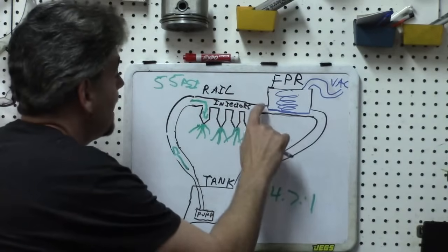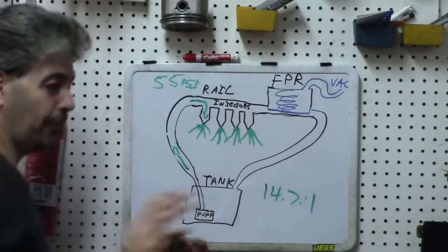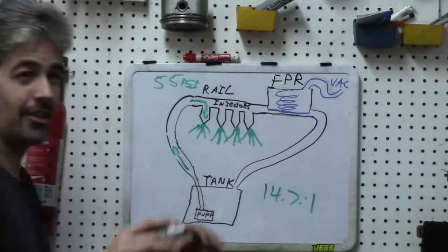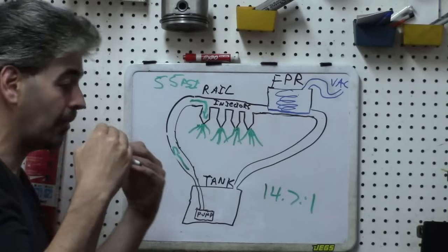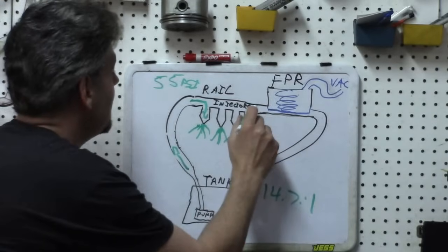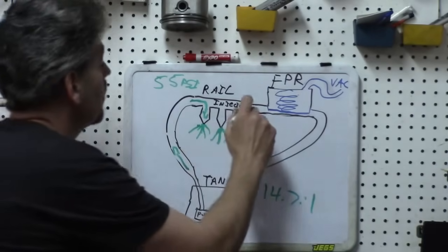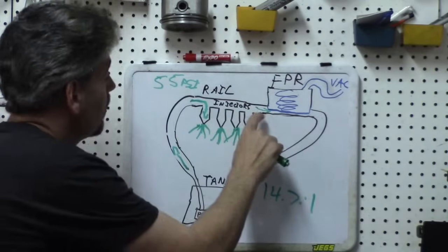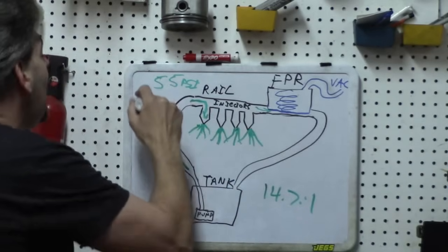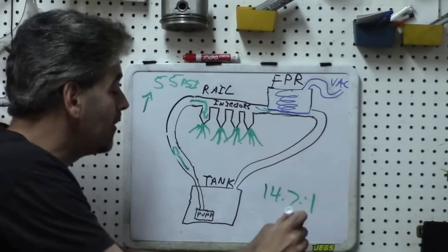You can see that what we've got here in blue is a diaphragm, and the diaphragm is connected to a spring. I know for those of you that are engineers or professional automotive technicians, you've probably been trained on this, and it's not exactly like this, I know, but the idea is to get the theory of understanding here. This is not an engineering class. But the idea is, by default, the fuel pressure regulator diaphragm is going to want to be closed to greatly restrict the fuel flow. And of course, this would create a higher pressure in the rail. And by default, that is where you would be at.